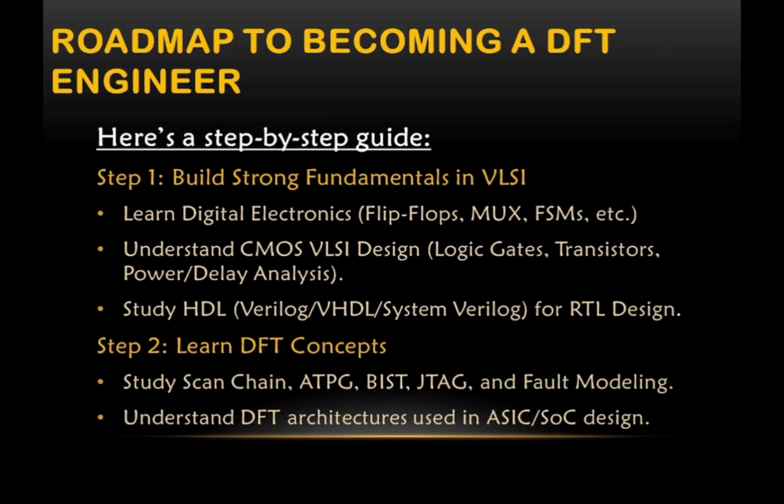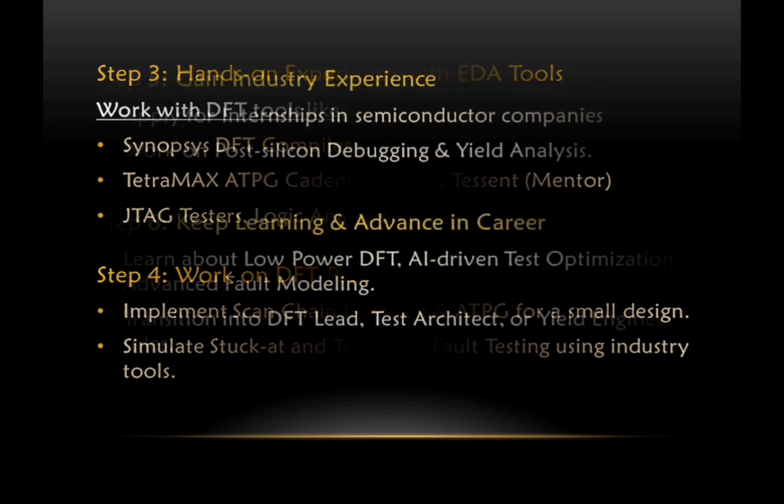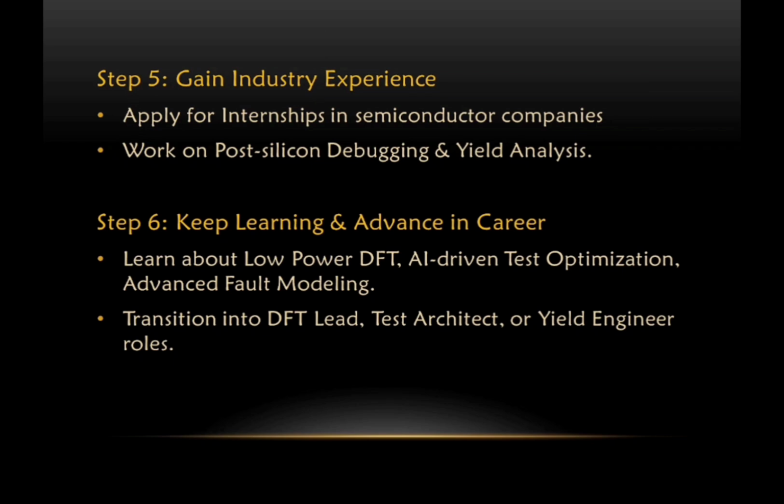Next step, learn DFT concepts like scan chain, ATPG, BIST, JTAG, and fault modeling. We need to understand the DFT architectures used in ASIC or SoC design. The next step is hands-on experience with EDA tools, like Synopsys DFT Compiler, TestMAX, and JTAG testers. We need some experience to gain knowledge of EDA tools. We should work on DFT projects, like implementing scan chain insertion and ATPG for a small design, or simulating stuck-at and transition fault testing using industry tools.